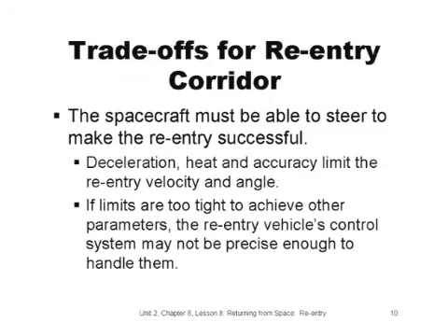As you can see from all these requirements, a re-entry vehicle must walk a tightrope between being squashed by too much deceleration and skipping into space with too little deceleration, between burning up or freezing, and between accurately hitting or missing the target. This tightrope is actually a 3-dimensional re-entry corridor through which a re-entry vehicle must pass to avoid skipping out or burning up. The size of the corridor depends on the 3 competing constraints, which we know are deceleration, heating, and accuracy.